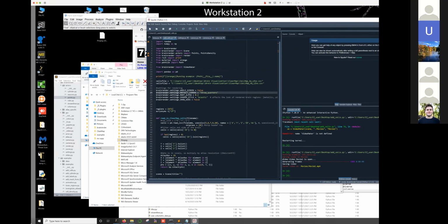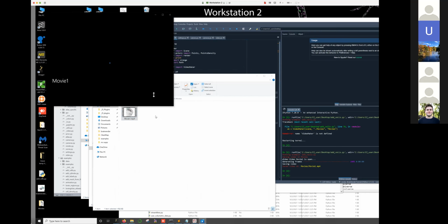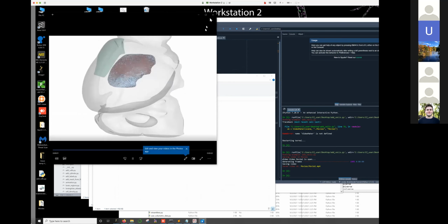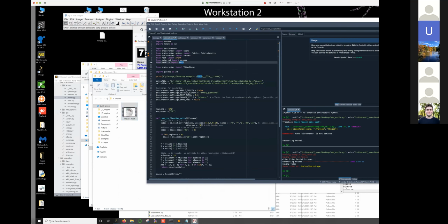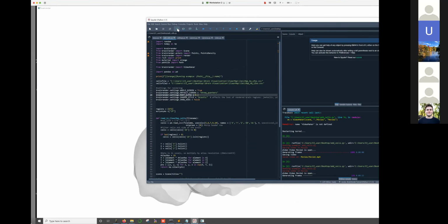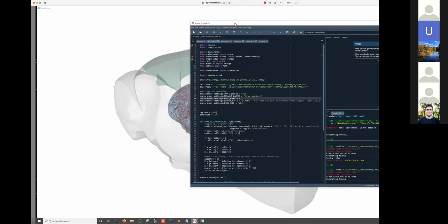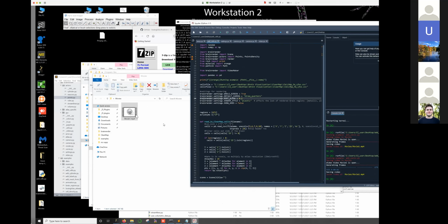Yeah, so I guess I should have, movies. So just a tip, this is the movie I just created. I find that, if you're not using the full screen, they come out kind of looking squashed like this. So if you're trying to render them a little bit more how you'd like them to look, just temporarily put this back to true, and that will give you a much better result. I'm just going to run it again. Okay, and now I have